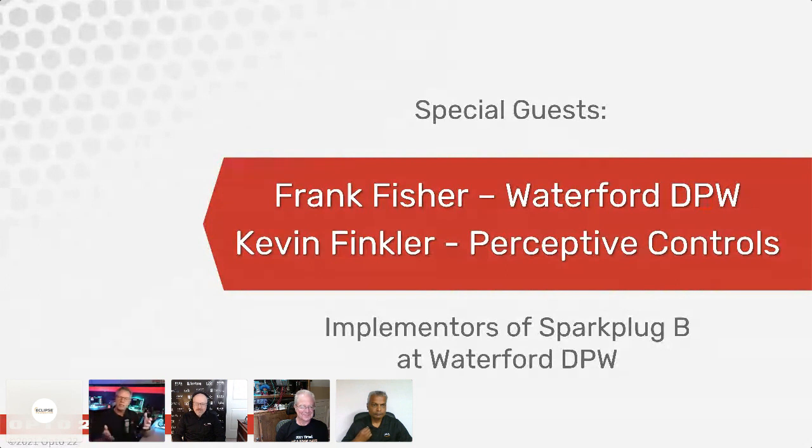But the biggest challenge, honestly, is that a lot of people, particularly in SCADA, are very used to the idea that they need to reach out to devices and poll them for their status before they can do anything else. That is a directly coupled one-to-one connection, something that many in the SCADA industry are frankly very familiar with. So when you turn that model upside down and say, hang on, how about the devices in the field let SCADA know when they have a change? That's a little bit difficult for people to understand, at least at first. But once you see it in action and you're not giving up performance, you're actually gaining a whole bunch of benefits, then the lights kind of go on.